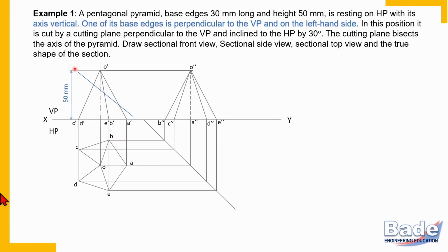Now let's assume we have cut object in this orientation, and this is the retained portion. Now observer is watching from top, let's assume. Now in the top view, remember section is newly generated surface because of the cutting. So section is visible from top.